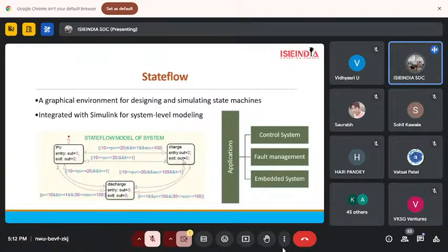This condition we would have to write ourselves in Simulink. You can write it in Simulink, or we can go for Stateflow, where you can implement a graph. If the rotor speed is 30 degrees, you should turn on one and two. You can write the code in Stateflow. After 30 degrees of rotation, you need to turn on two and four. So it should be like a flow, like a chart, where there are conditions and transitions from one phase to another. This is the way we go for Stateflow.